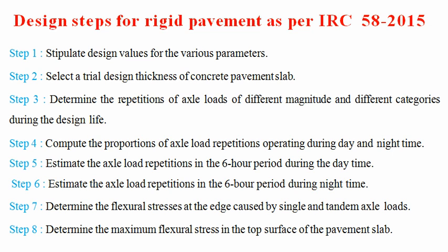Then compute the proportions of axle load repetitions operating during the day and the night time. Next is to estimate the axle load repetitions in the 6-hour period during the day. Then the sixth step is to estimate the axle load repetitions in the 6-hour period during the night time.